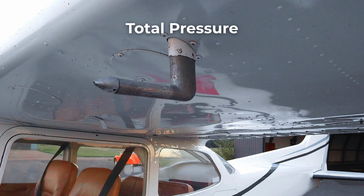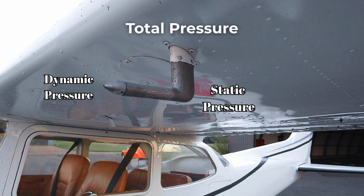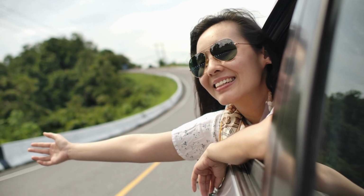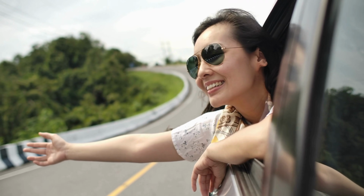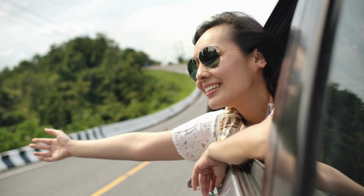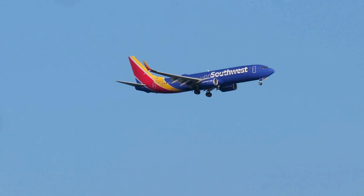Total pressure, also called Pitot pressure, is simply the sum of static pressure and dynamic pressure. Think of sticking your hand out of a moving car window. Your palm feels both the still air, static pressure, and the air hitting it, dynamic pressure. Together, that's total pressure, just like what an aircraft measures in flight.